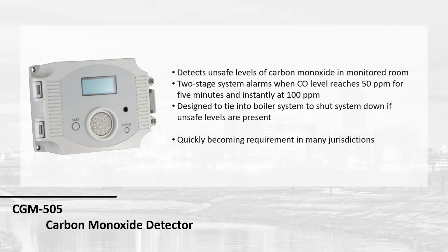The biggest pushback I get is from the BMS guy. He says, "Oh, I got a CO monitor sensor, and we'll shut it off through the BMS." It takes nothing, and Austin could attest to this. If you lose comm to your boilers, the boiler says, "Hey, I've lost communication. Let me just go into local mode," and it turns on its own, based on its own thermostat. So you've basically bypassed that safety device. So always recommend it go directly into the auxiliary limits.